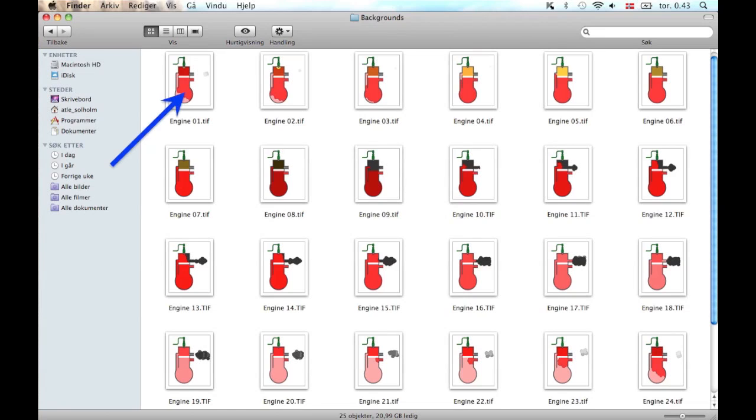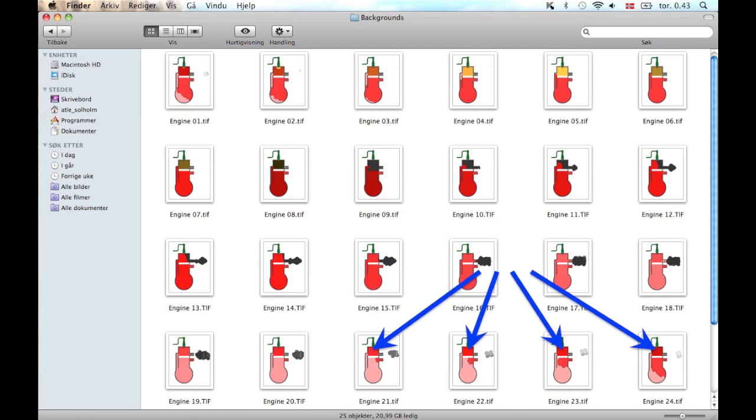I've illustrated how the fuel mixture enters the crank chamber below the piston of the engine, as the crank chamber is going to act as a pressure chamber, and I've illustrated how the air-fuel mixture next travels through the scavenging port into the combustion chamber. Next, I've used an increasing red tone to illustrate compression of the air-fuel mixture.